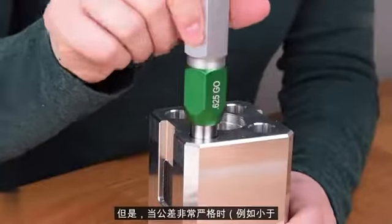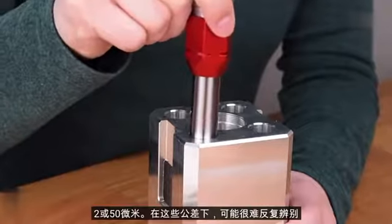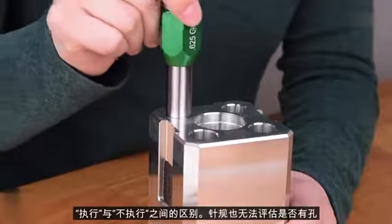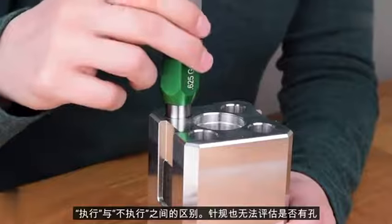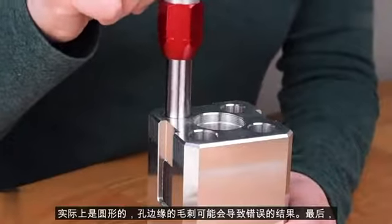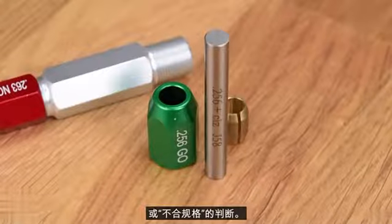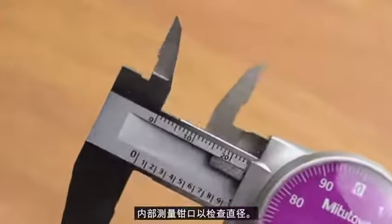However, plug gauges become problematic when tolerances are very tight, like less than 2 thou or 50 microns. At these tolerances, it can be difficult to repeatedly discern the difference between a go and a no-go. Pin gauges also can't assess whether a hole is actually round, and burrs on the edge of the hole can create a false result. Finally, you'll often need an actual numerical measurement of a feature instead of just an in-spec or out-of-spec judgment. In these situations, you might be tempted to reach for your calipers and use their inside measurement jaws to check a diameter.